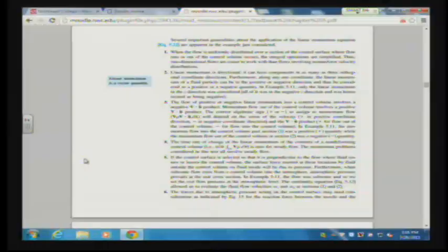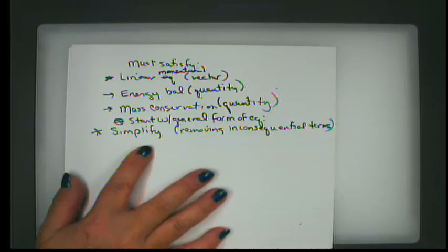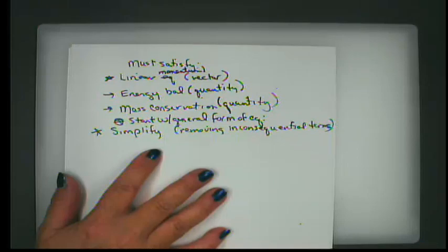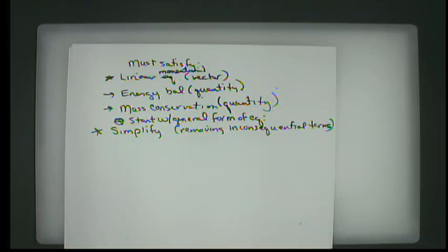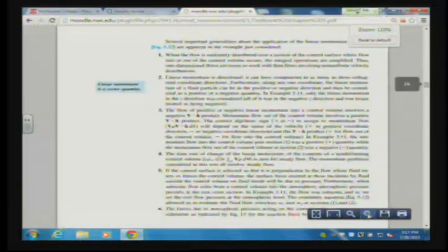So, for example, what I mean by that is if you have water hitting a vane and the control volume is moving but not deforming, you take out anything that has a dV in that control volume, which would then remain constant. It would come outside of the integral. So simplifying is always dependent upon the system itself. And it's just really important to remember that, because otherwise you can make yourself crazy with these huge, sometimes unsolvable equations. Point number 2 tells us that linear momentum is directional.